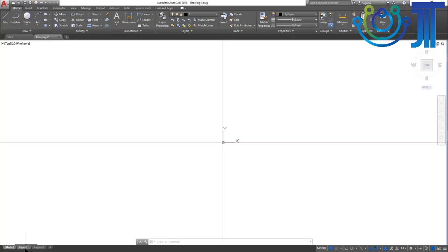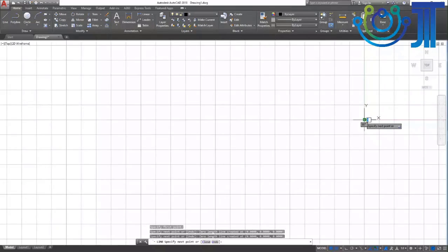And now the next part. Once you have created this, there is a modeling area here where you can see different functions: display, draw, grid. Here different functions are there. This particular function is called the ortho mode. Ortho mode means that when you click a line, the line will go in a particular direction. Okay, so this is ortho, and if you remove the ortho, it will not move in a straight line. And these are the various types of functions that you can see here.